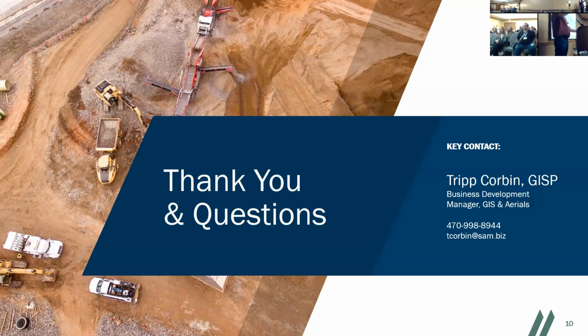The other thing you can get is people that say it's absolutely in North Carolina State Plane NAD 83, and you're like, it can't be. It's not coming in right. They tried to project it from 27 to 83, and instead of using the Project tool, they used the Define Projection tool and just created a new PRJ that was wrong. I've encountered those fun things.